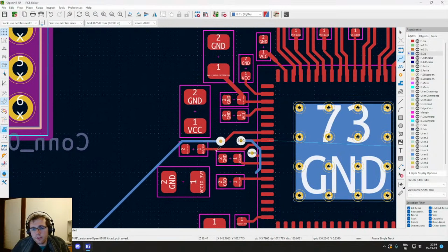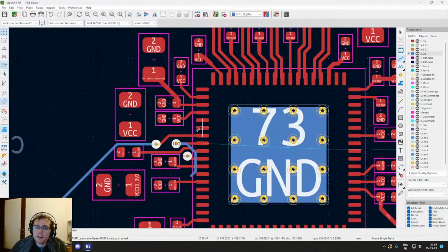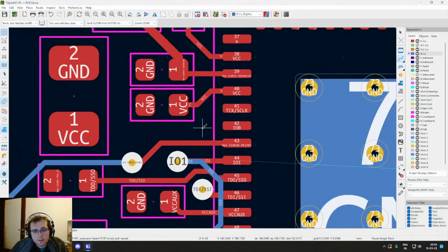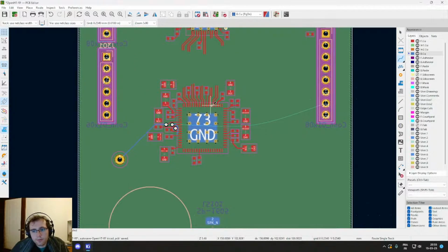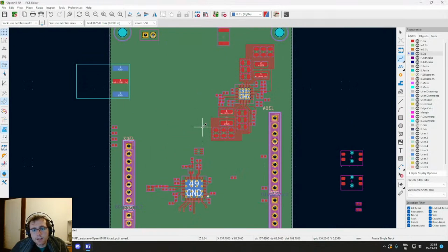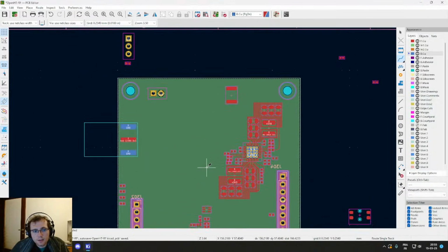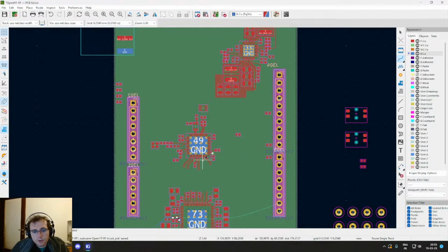So first step is just basically fanning out the connections, do a first routing, and then we are gonna refine it and pay attention to all kind of issues that can arise with pad routing. Pay attention not to route tracks on split planes and so on. So it's not shown here, but it's a 4-layer board, and the second layer is plain ground. But that's what is usually done with 4-layer boards.